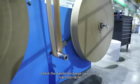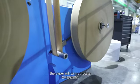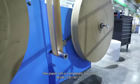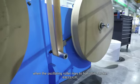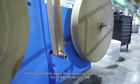Check the handle discharge swing roller. Check the pressure of the oscillating roller. The paper roll cannot rotate when the oscillating roller is lowered to the minimum. The paper roll is completely loosened when the oscillating roller rises to half of its stroke. If not, you need to adjust the pressure of the oscillating roller.